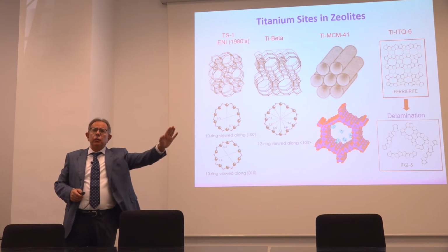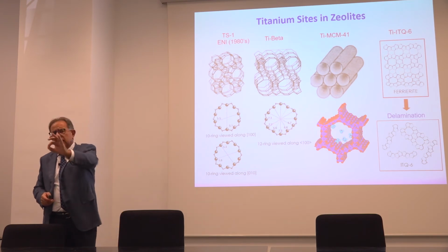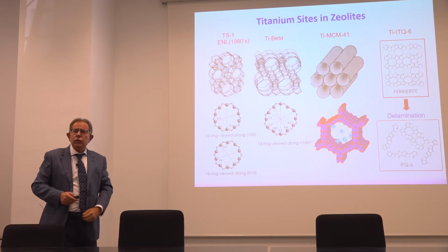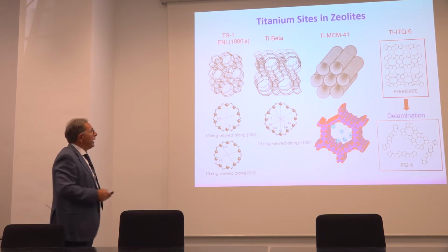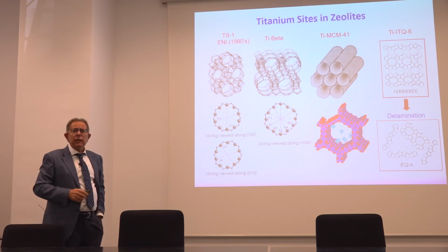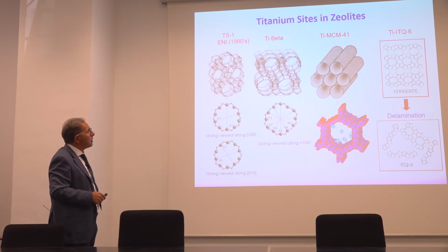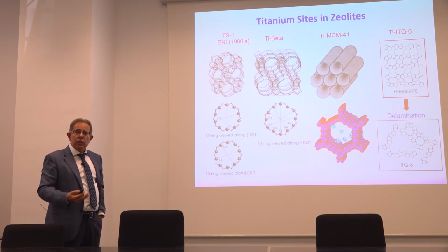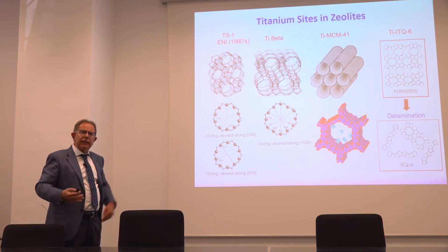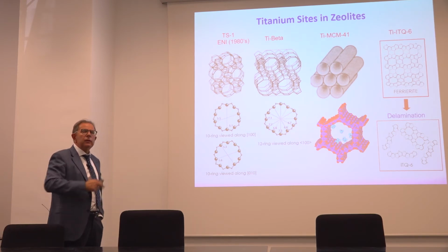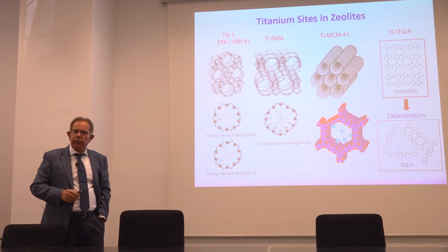Metals, titanium, well-defined titanium, tetrahedrally coordinated. Any technology achieved to do that in tetrahedral positions in ZSM-5. That was a medium pore zeolite, 5.5 Angstroms, and then the purpose was to be able to expand that into larger pore zeolites in which we could process larger molecules.